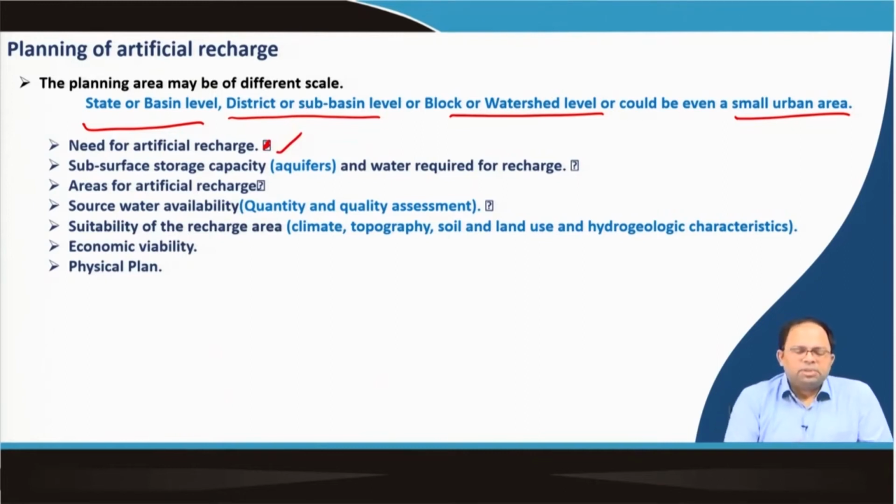Second is subsurface storage capacity and water required for recharge, and whether both are available or not. That means, we are thinking of recharging a particular aquifer, but is there subsurface storage capacity in this particular aquifer? And this is one. The second is, is there adequate water required for recharge? That means, we will say we will recharge, but is there excess water available to recharge? So, these are the second thing that we need to ascertain.